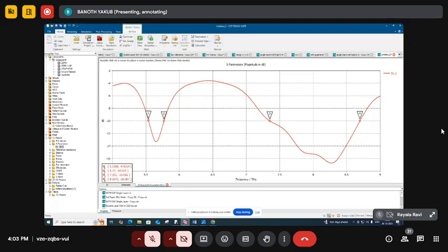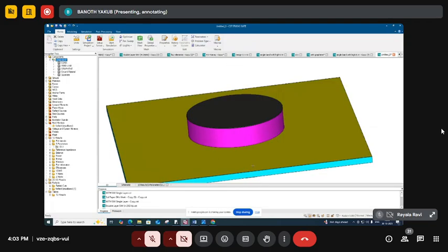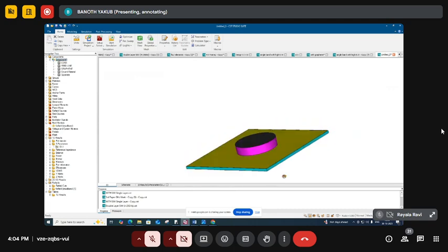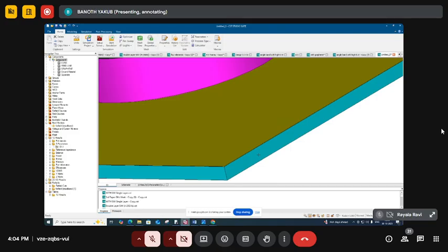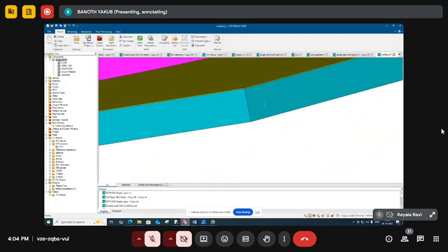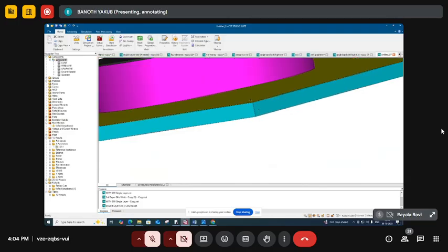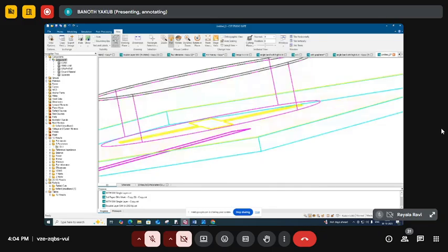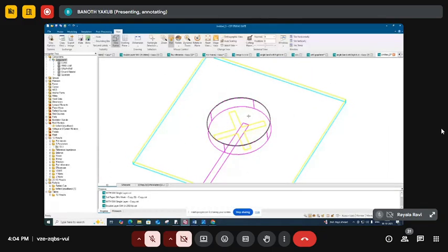So now I go to conclude my session. Today's hands-on session is antenna design at terahertz frequency. The bottom layer is the microstrip feed line we designed, and two layers are designed here, the substrate layer and the top ground material layer. In this design we made one cross slot.